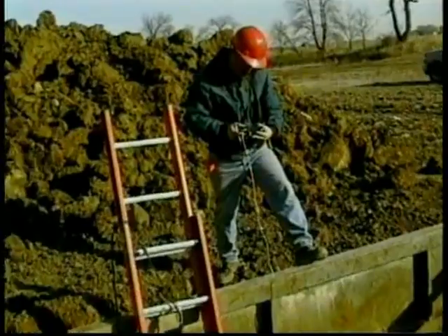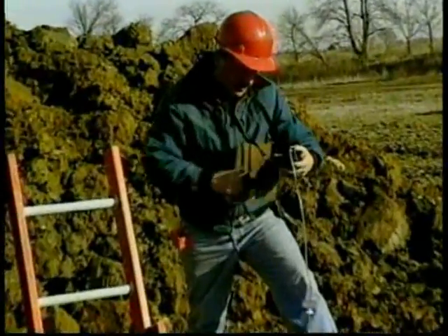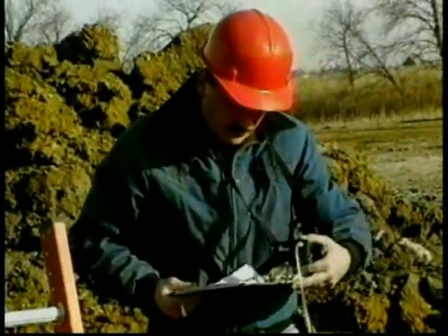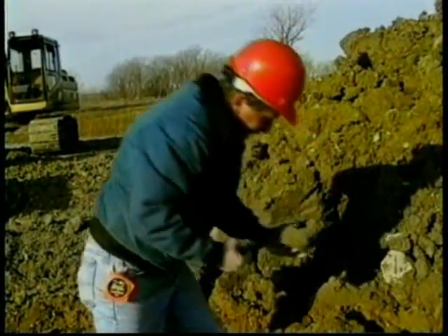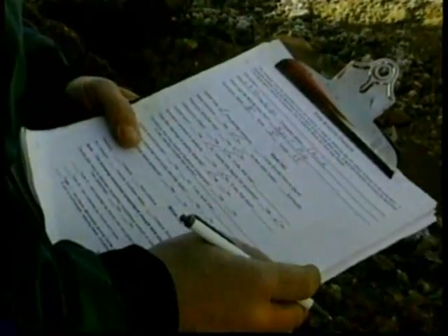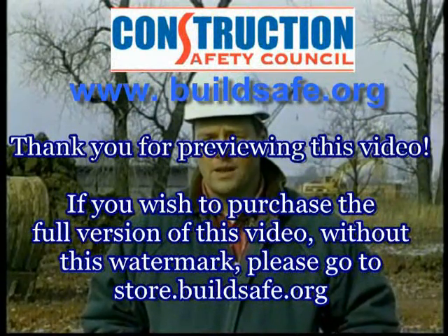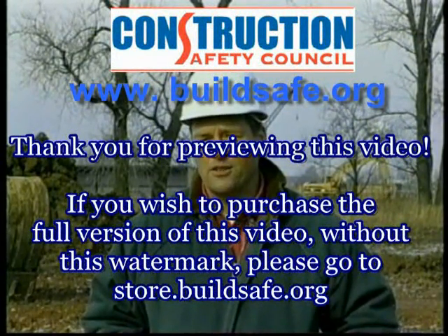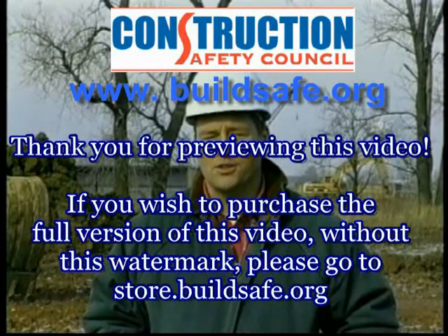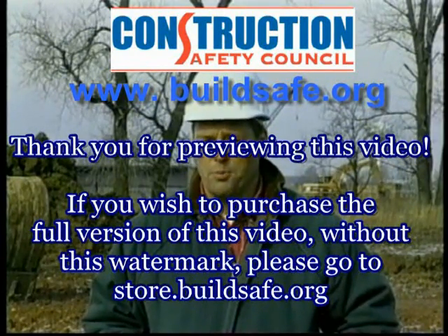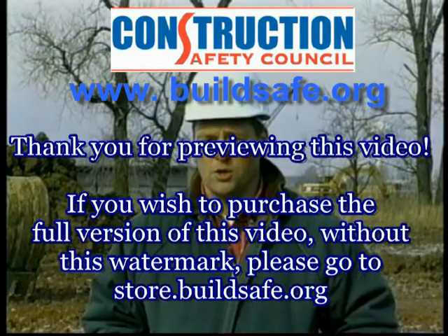From the beginning to the completion of the work, make sure that the soil analysis, daily inspections, and selection of the protective systems are done by a trained, competent person and fully documented. The documentation is insurance that an OSHA inspection will find the job is being done according to the OSHA standards. But more important, it will be evidence that you've made safe excavation conditions your primary concern. And there's nothing more important than the safety of your workers on the job.